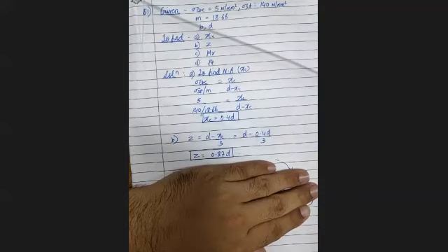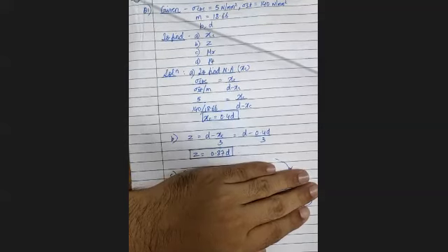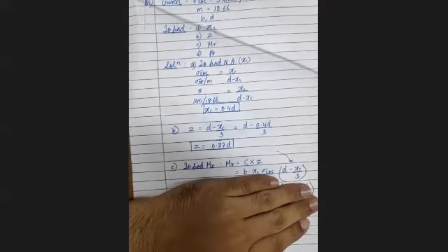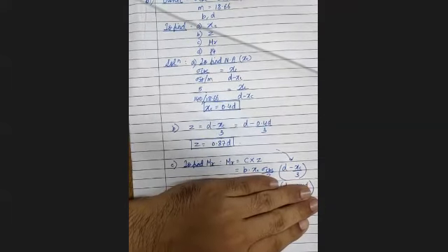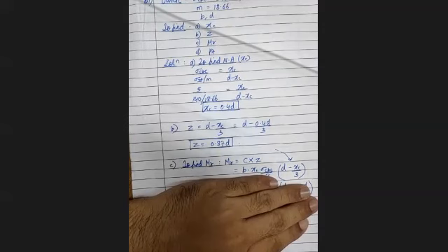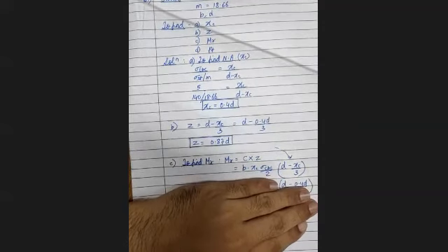So you can make that into 2 digits also, no problem. Or you can keep it in 3 digits also. So now we got the 2 parameters. Now let us go for the third unknown, that is MR. So MR is given by C into Z. So C is nothing but B into XC into sigma CBC by 2, into Z is D minus XC by 3. So you have already got the value of Z, so you can directly substitute the value of Z.